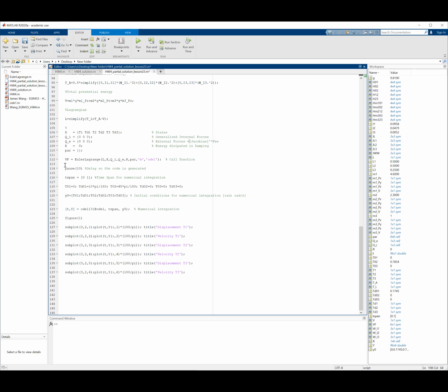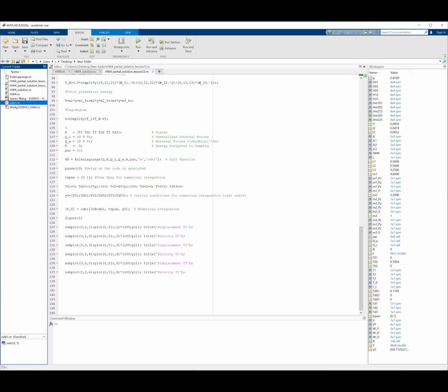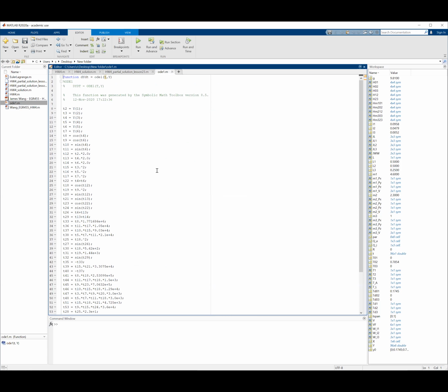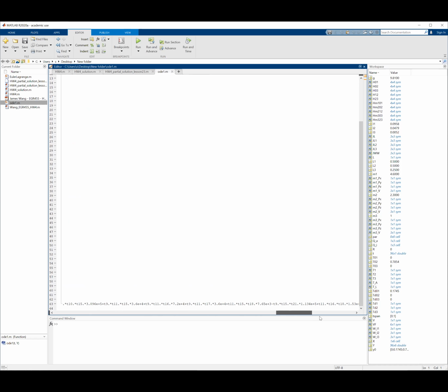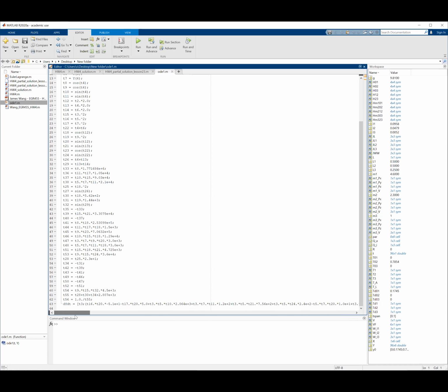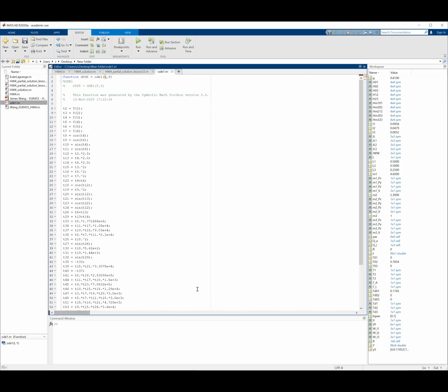If you look at the way the Euler-Lagrange and ODE1.m are formulated, let me show you what I mean. If you look at this ODE1, it does not give you a direct option to add the external torques. So you will have to go to this code and manually change this last line, line number 63, so that you can have time varying torques.